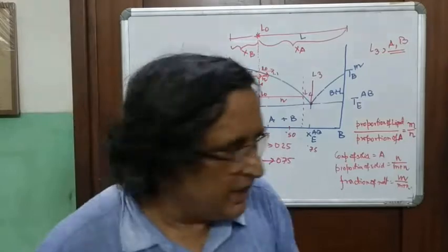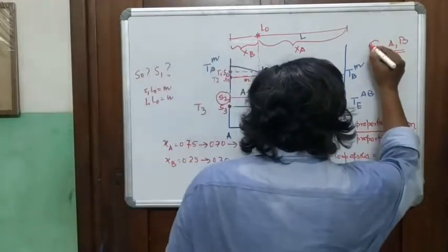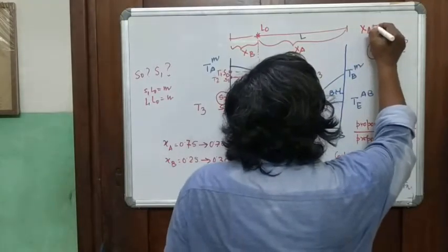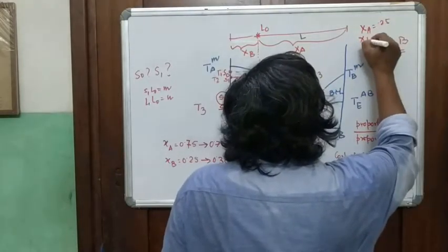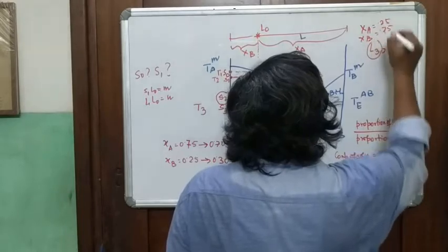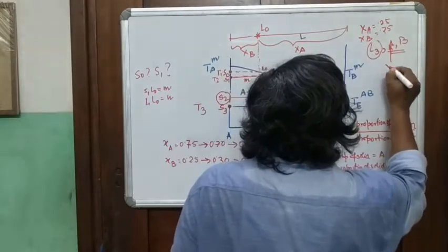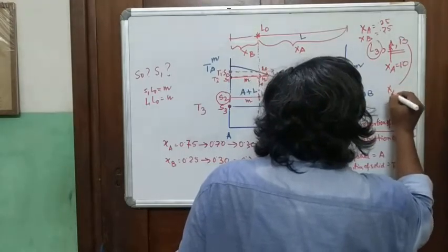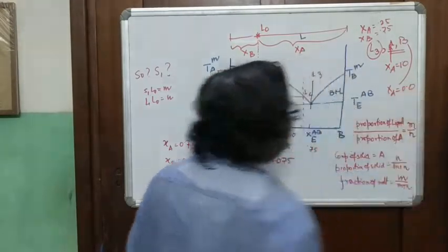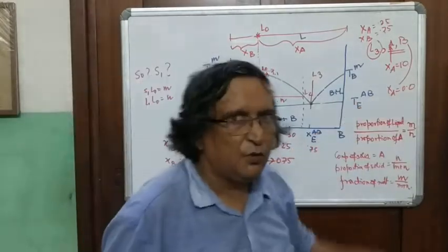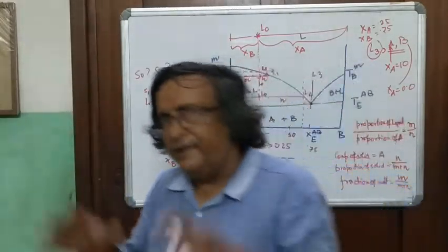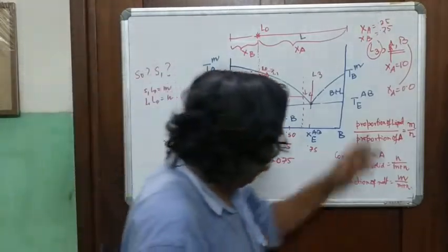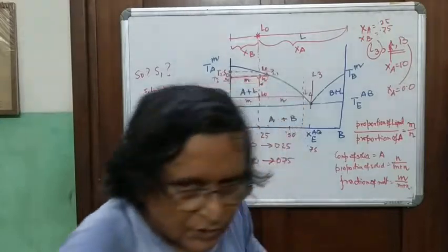Think again. There are three things in equilibrium. A liquid L3 with XA equal to 0.25, XB equal to 0.75, it will be in equilibrium with A, where XA is equal to 1.0 and B where XA is equal to 0.0. That means XB is equal to 1.0. This will be the condition. This will be the condition at the eutectic. So what will happen?